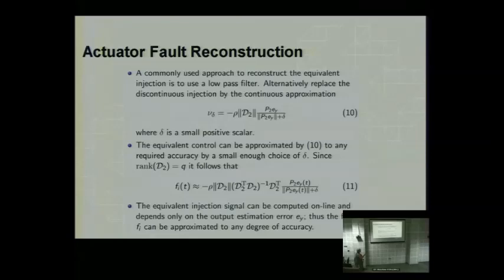we can reconstruct that fault exactly in real time from knowledge of where script D2 comes from. It's just part of the transformation matrix. This is the size of the switch in the observer. This is the parameter P2 relating to the stable matrix A22S we picked. And here, I may well want to use a bigger delta than I might want to use for the observer implementation. For the observer implementation, I can use delta equals 0.